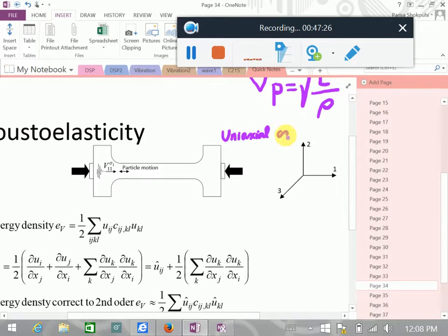So this is a uniaxial compression. We are applying a strain U1, or UX. I've used X and 1 interchangeably, X, Y, Z. And what we are looking at is p-wave velocity V11. Remember, 1 refers to the propagation direction, the other one refers to the particle displacement.